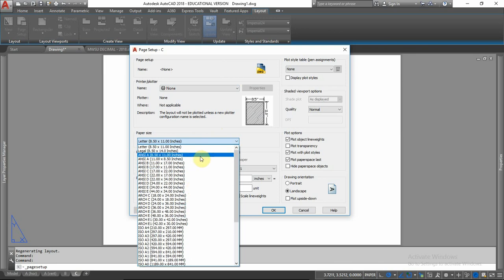Now per the media sizes handout sheet that we went over, plus is on Canvas available for you, I've filled in some of the dimensions. You're going to go down here, and instead of ANSI, for example, ANSI I see 8.5 by 11, 11 by 17, but your C is truly the standard size, 17 by 22, 22 by 34, and so on. Instead, use architectural C, 18 by 24 or 24 by 18. Now you may have to manipulate this. In this case, use the 18 by 24, and then we'll select landscape. And then D, 24 by 36.